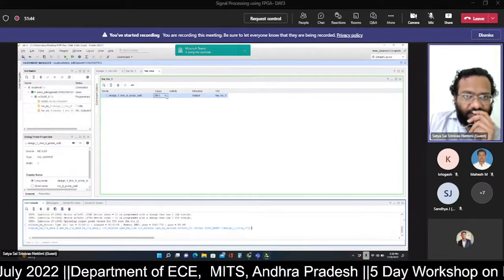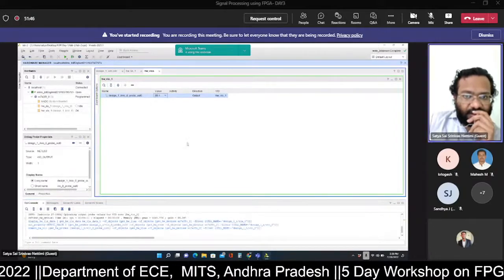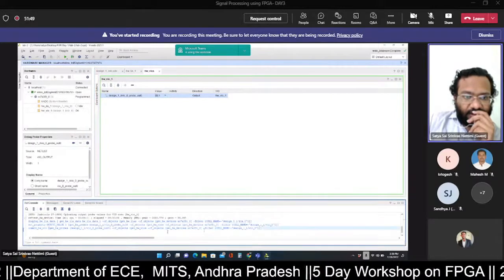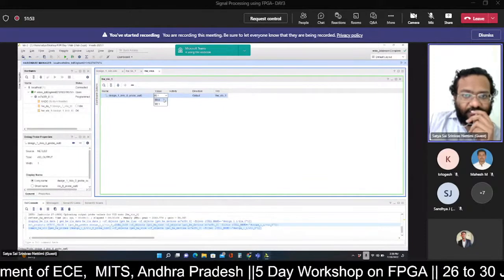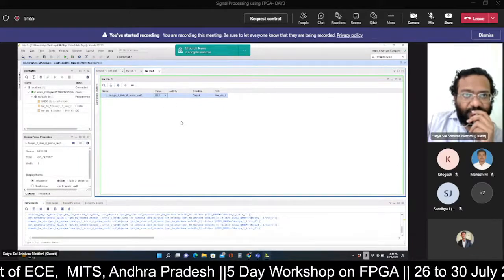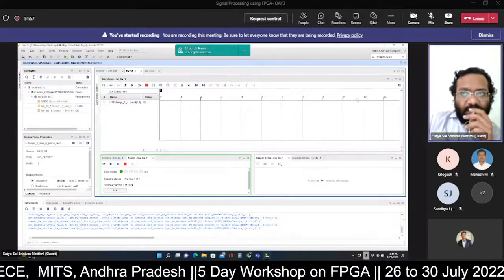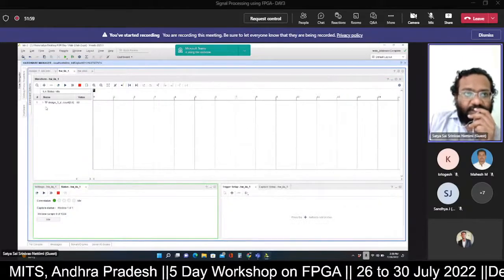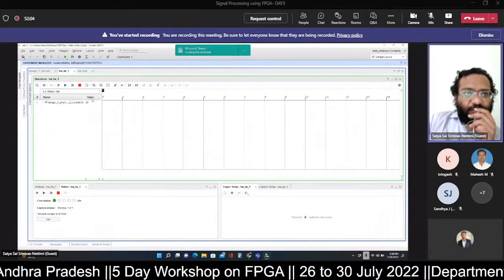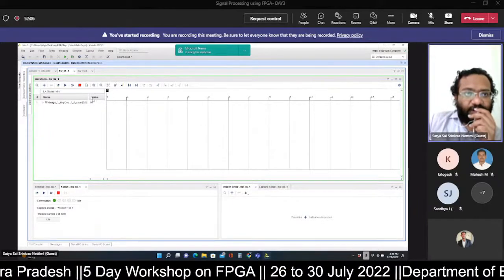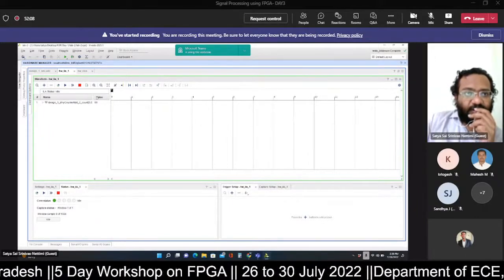If you try to give a new value, again you will get a new Tcl command, whenever you are passing data. So first we give a 0 value. Now you go to the ILA. In the ILA, you can see by default, since we connected only one output to our ILA probe, that one output is available here.